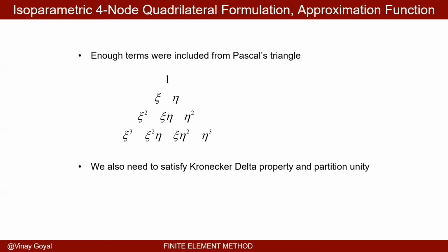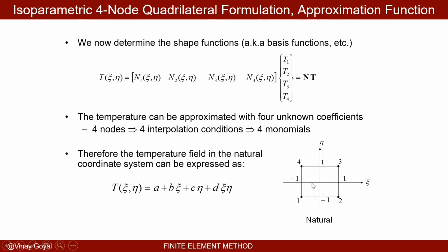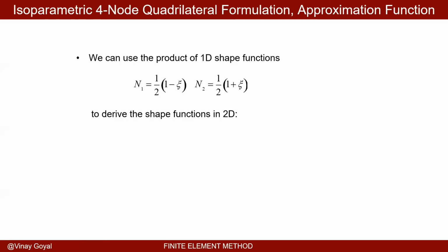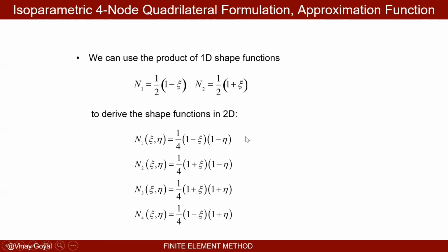Let's look at shape function number 1 to see where that was. It's at this little left corner. So that's -1 and -1 for xi and eta. So if I put xi and eta of -1, I get 2 and I get 2. 2 times 2, 4. 4 divided by 4, 1. But you can see there's 0 at all other nodes. When I plug in these coordinates here, I get 0.